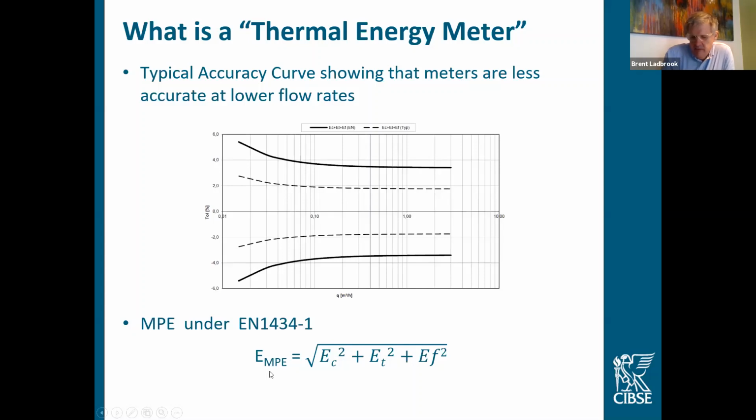The key takeaway from this slide is really that there's no point in having an extremely accurate flow sensor but very inaccurate calculations or very inaccurate temperature probes. I sometimes see people go, well, I'll put in an accurate flow sensor and then I'll write some code in my BMS and calculate this myself.